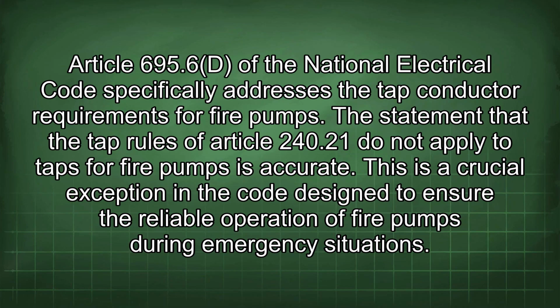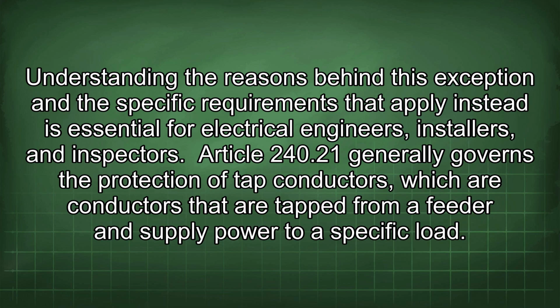695.60 of the National Electrical Code specifically addresses the tap conductor requirements for fire pumps. The statement that the tap rules of Article 240.21 do not apply to taps for fire pumps is accurate. This is a crucial exception in the code designed to ensure the reliable operation of fire pumps during emergency situations. Understanding the reasons behind this exception and the specific requirements that apply instead is essential for electrical engineers, installers, and